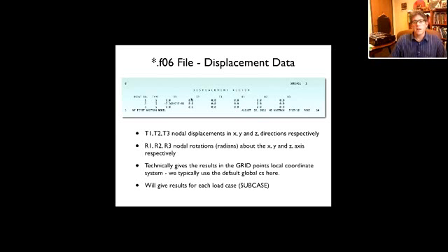And again, if you specified another coordinate system, CID, for that particular grid point, it will resolve these displacements in that coordinate system. If you leave that blank, it's going to use global, and these are in the global x, y, z axes. Okay. If you have multiple load cases, there will be different displacements typically for each load case, and so it'll have the displacement for each load case or subcase listed separately. Here we just have one subcase, so you can see it just shows the displacements for the 3 nodes for the one subcase.